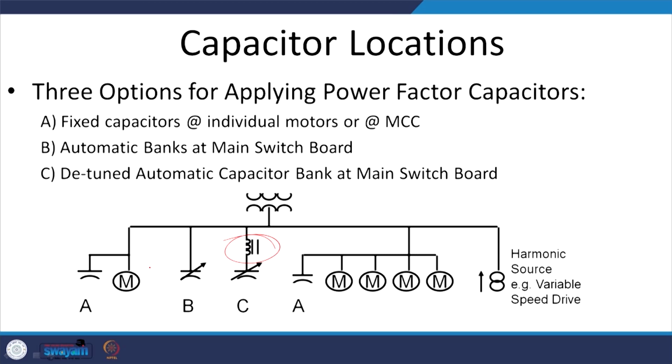So, what is very important now is the placing of the capacitor and its type. I have told you a little early that you have to have a variable capacitor, because you have some harmonic sources and that may corrupt this capacitor, and thus generally there are 3 options for applying a power factor capacitor.